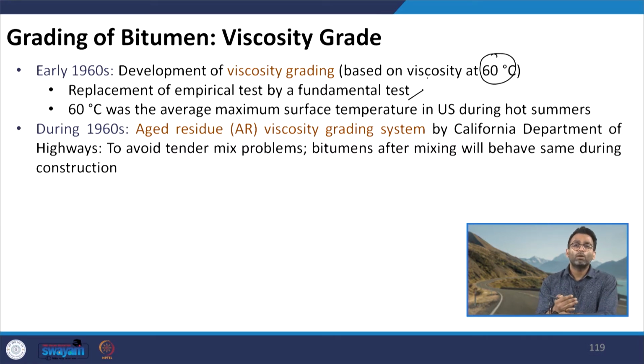but they did this on the short term residue or the aged residue, okay. And this was done because they found that some of the binders, in the unaged condition, have the same consistency. After aging, after undergoing mixing with the aggregates, a few of these binders yield tender mixes. So, they do not compact properly under the rollers.